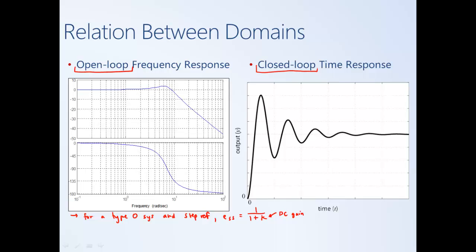So recalling this sort of expression which we derived earlier in a previous module, think about what aspect of the frequency response plot would tell us about a system's steady state error, what the steady state error is for a step input, for example. DC gain corresponds to a constant input, and a constant input basically has a very small frequency, a frequency of 0, if you will.